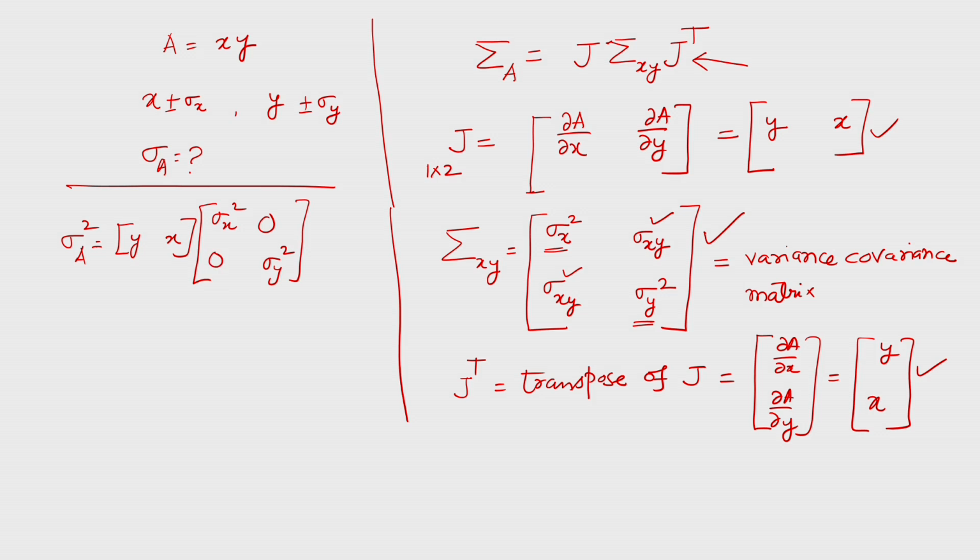Why? Because, as I know, if the observations are coming from the field, the covariances are generally assumed as 0. So I am assuming that I am measuring x and y using a tape, so it is a field measurement, and now I can say that covariances are 0 because both x and y are measured independently and they do not influence each other. Their errors are not influencing each other. This is the total matrix here.